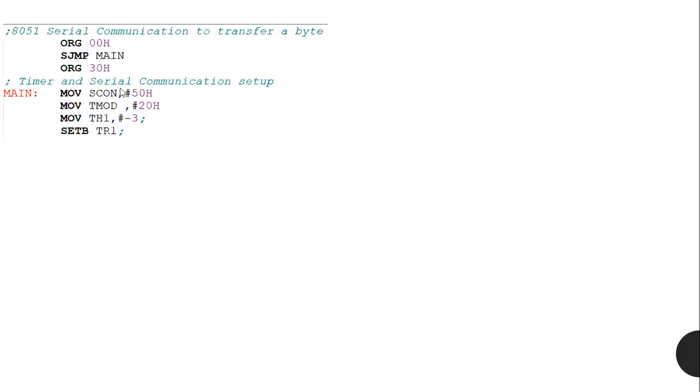It's an assembly language program. The first part of the program gives the assembly directives, and skips the main part by using another assembly directive, ORG 30H, so that we can bypass the interrupt vector table. And next, what do we have?